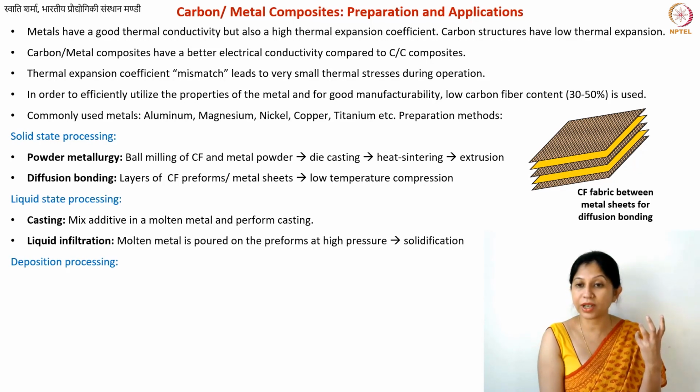Remember that you need to ensure that your metal does not immediately solidify. You may need to control its solidification. Therefore, you can play with the pressure parameters a little bit. So this is basically, again, your molten metal diffusing through the carbon fiber. The advantage that carbon fiber offers as compared to any other additive is that there is no expansion because of the heat, and no adverse effect on the structure of the fiber because of the heat.